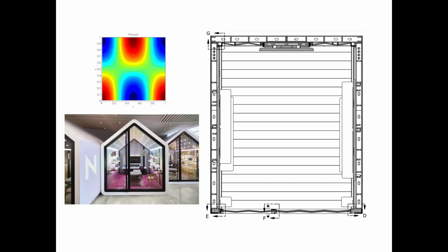But anyways, we had the sawtooth on the back to try to diffuse sound so we don't have reflections coming back. And then we had sawtooth up here, partly, so up here it was sound absorption. You see these kind of felt pads up here. We wanted it sawtooth because they liked the sawtooth look. They wanted to match that on the front, but also by changing the depths of it, we got lower frequency absorption. And then if any high frequency sound would be reflecting off the fabric facing, then it would be diffused. So that was some of the treatment we did in there.